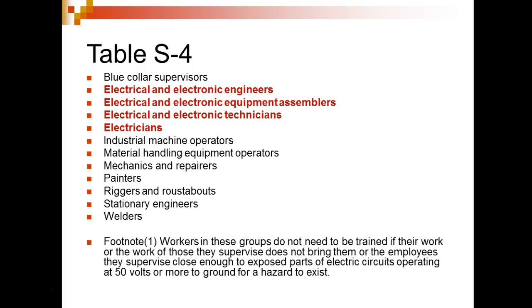Now, work on means to replace things, right? Of course, testing, we can test on live equipment, but we can't do what? We can't work on. Y'all understand the difference? So we can't replace things on a live circuit with power applied. We cannot rewire things. We cannot cut wires. We can't do anything like that with power applied. But we can test it, right? Y'all understand?